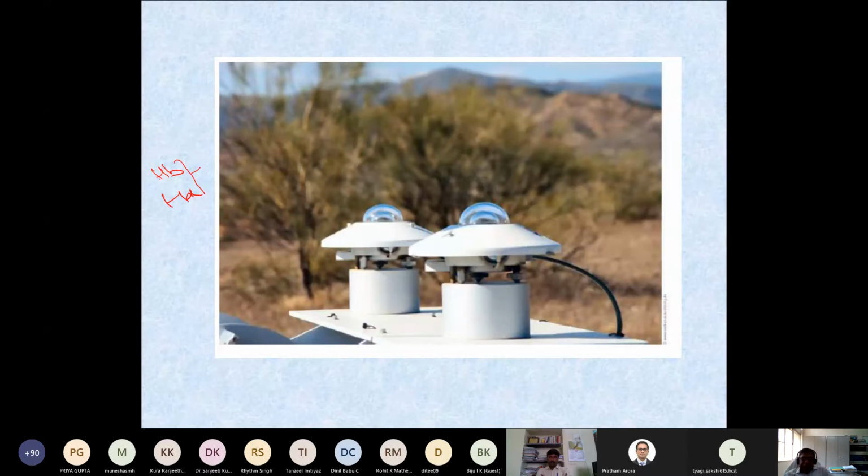Then you have the total solar radiation, you subtract the diffuse radiation, and the beam radiation can be separated. But during measurement, the weather monitoring stations are not using the mathematical expressions or theoretical correlations. They measure beam radiation and diffuse radiation simultaneously.